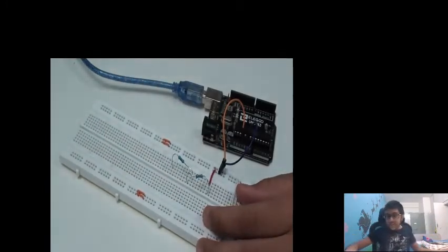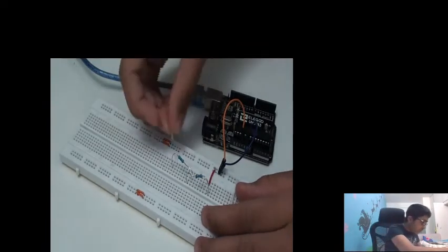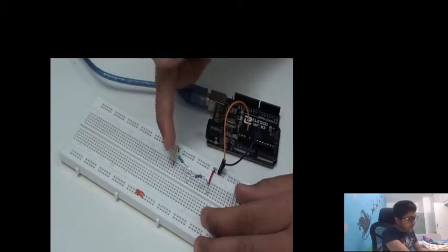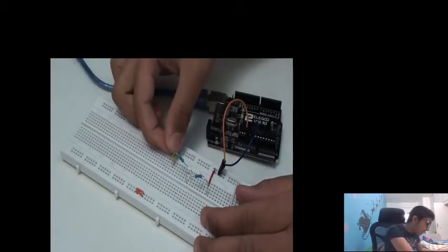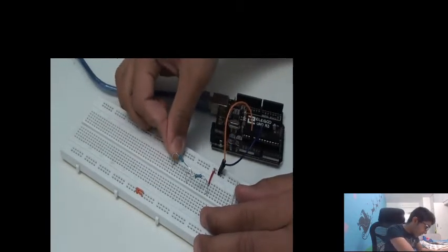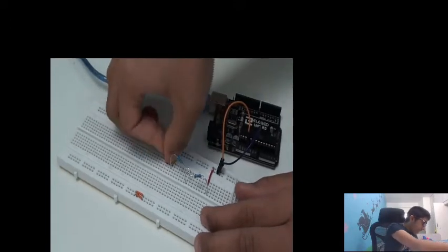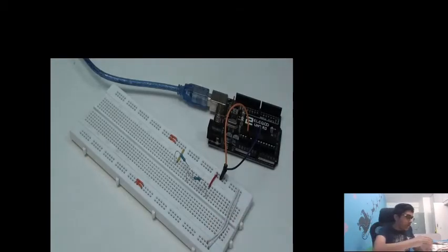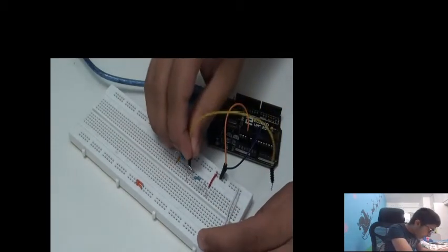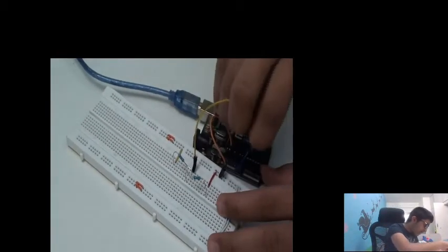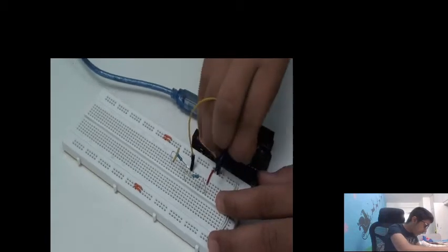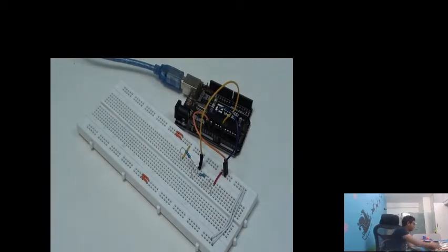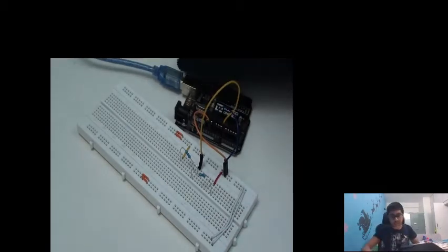And lastly, we're going to ground our circuit. So we're going to take a wire from the other end of the 5k ohm resistor and connect that to ground. Now, like I said, in between these resistors, we are going to put a wire. We're going to connect a wire and drag that straight to analog pin A0. Now, let me explain the mathematics of all this business.